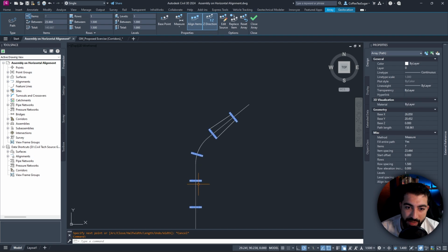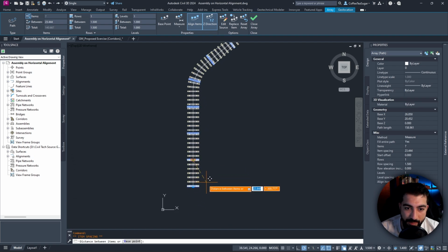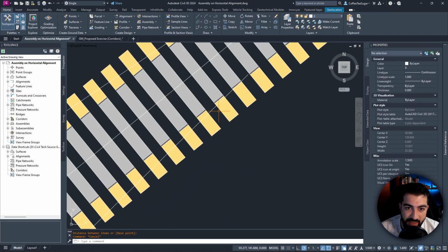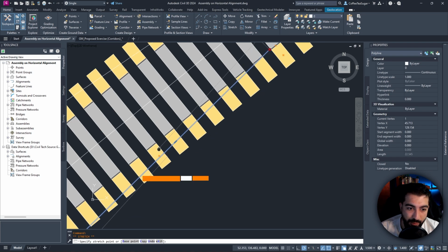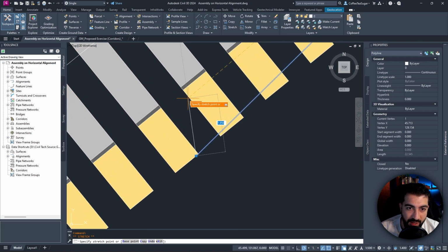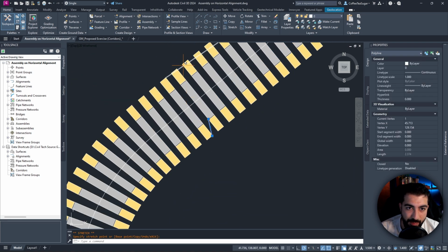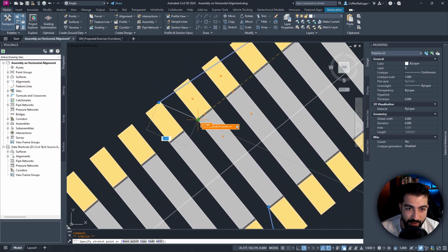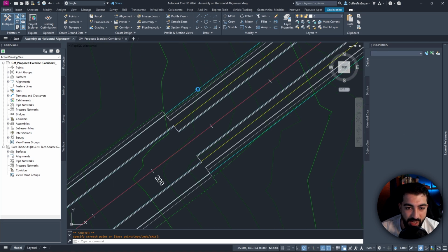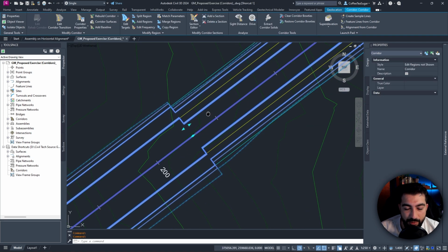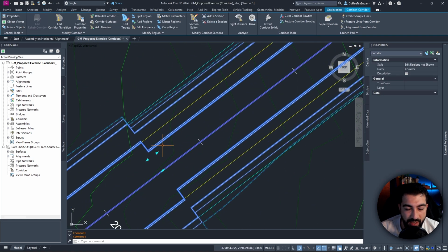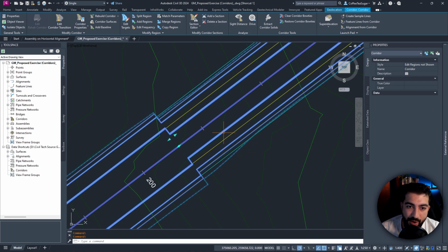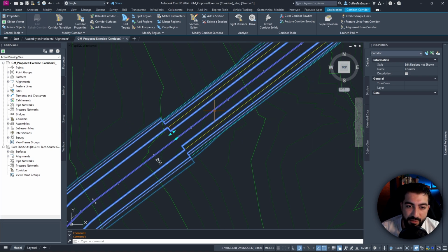But when we increase the frequency to 1 meter, the line where we started the region becomes like this, but obviously we increased it to 1 meter, so therefore this is way closer. So it made the dogleg shape of this. To smooth this out, what I usually like doing is just add a transition to it, which we will cover again in a different tutorial. I just wanted to show you that this is how you can control different regions.